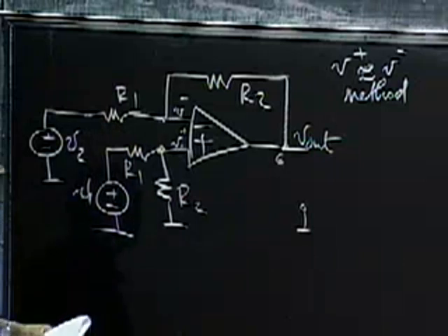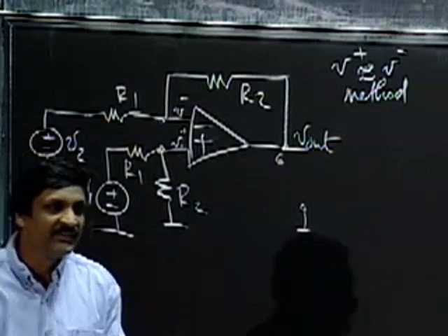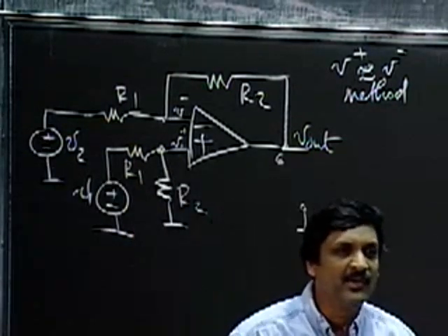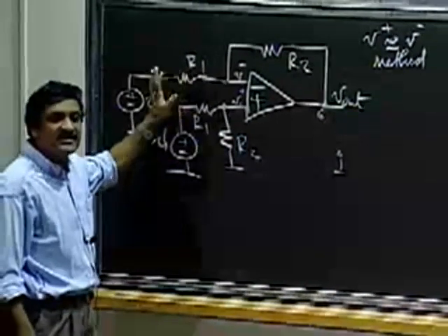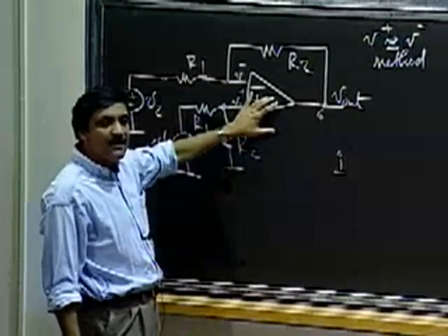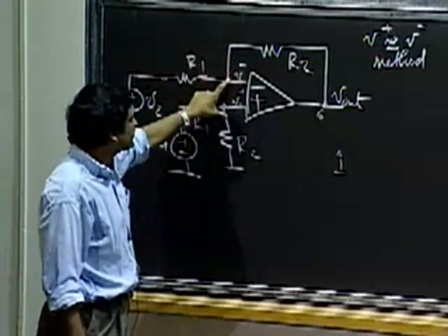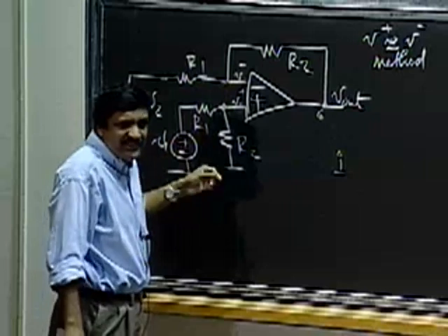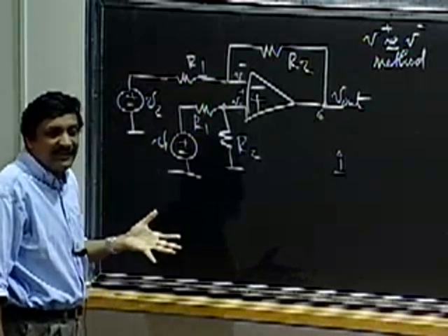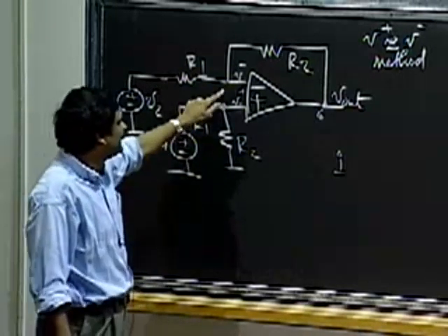So if, for example, V plus increases, the output will increase, and so will the voltage here, and tend to make these two equal. So what we can do, being rather tricky here, is say, look, if we know for a fact that under negative feedback, the op amp is going to engineer these two node voltages to be more or less equal, then why don't I just use that fact to begin with and analyze my circuit assuming that is true?